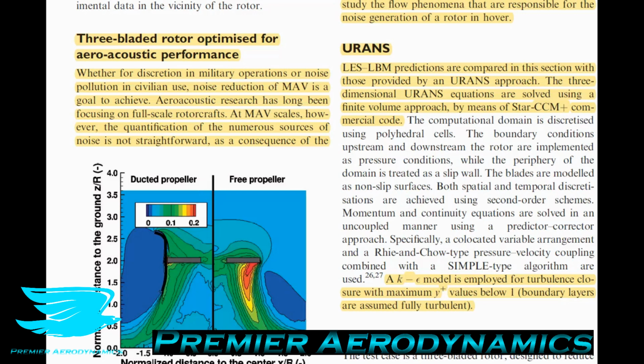For example, about 8 years ago or so, I had a friend who was researching noise coming from airfoils, and even with DES, he was having such a hard time just getting a basic, accurate noise spectrum from an airfoil with OpenFOAM DES. It wasn't matching experiments very well. He got the first, the dipole, quite well. The quadrupoles and the octopoles were well off.